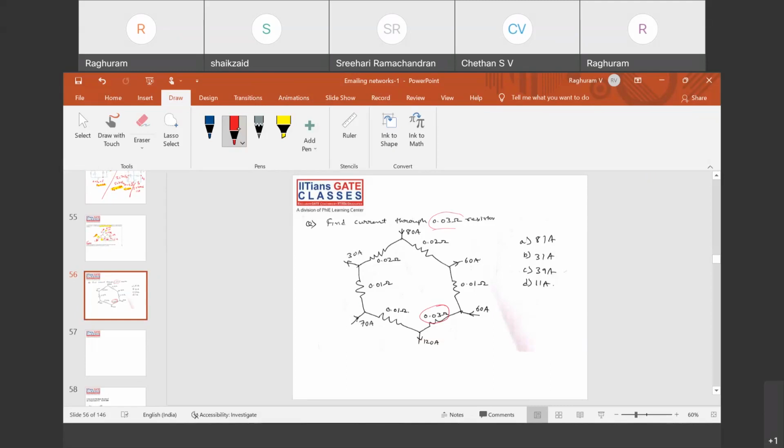A bit tricky question. If you want, I can try it. Otherwise, I'll give you some hint. So what you have to do is apply KVL in this loop. Assume a current of I here. What will be this current? Let me write down the currents and the equation. You have to find I.